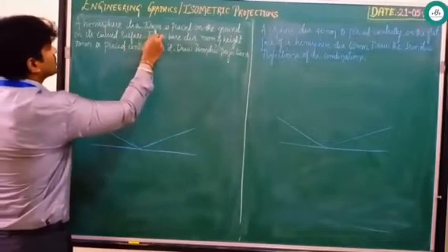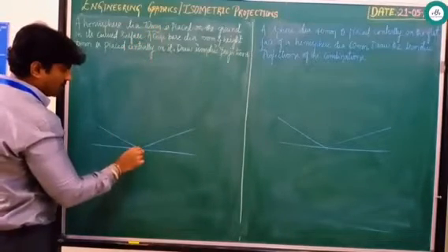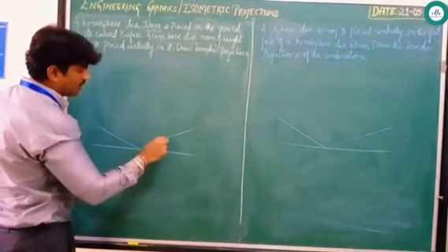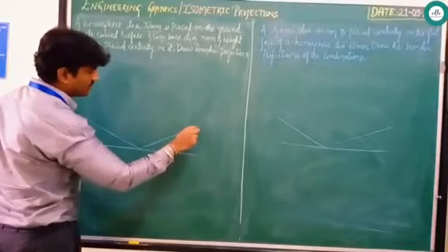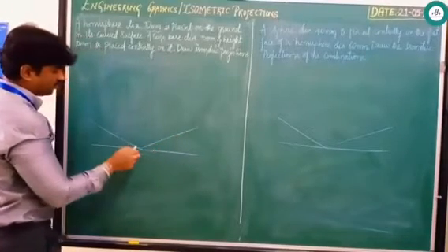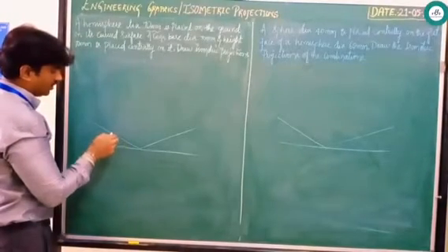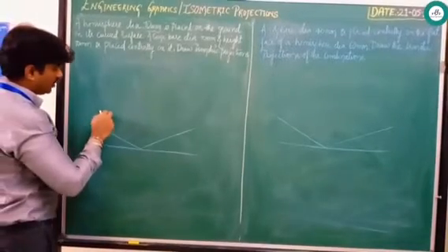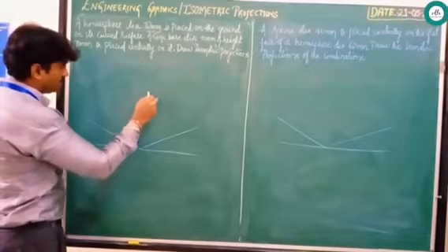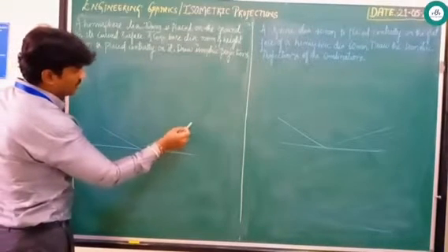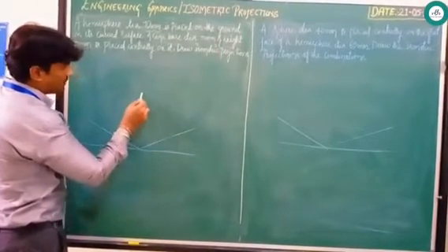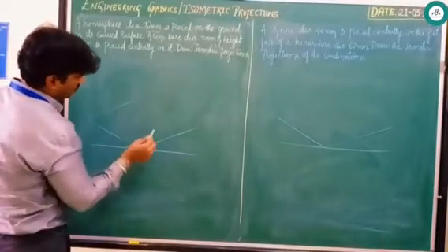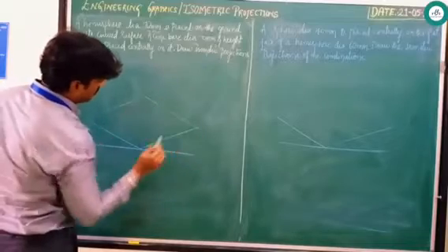It is 70 mm. So what you can do is, starting from this point, mark 70: 10, 20, 30, 40, 50, 60, 70 to this side, again to the left side 10, 20, 30, 40, 50, 60, 70, and again from this point in the same way. So you will meet up with a common point. So draw this. Next, join this way.